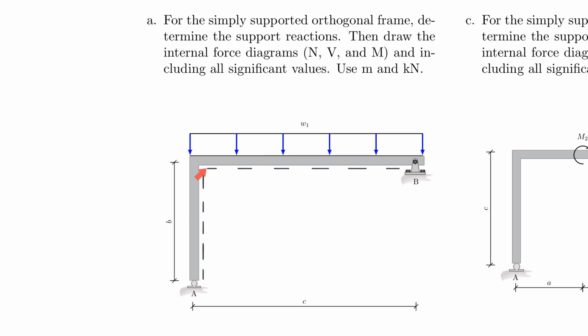So I suggest that for this frame, you just put it on the inside, and then I think everything else is as before. You don't need to solve the support reactions through 2 equations with 2 unknowns. In fact, the first one here you can find is the vertical support reaction at A. You just take the sum of the moments about this point, and then you have your vertical reaction. Then you can find the vertical reaction here, and there's in this case no horizontal reaction.